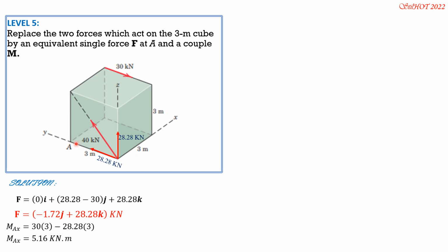MAY, because this is the AY axis and this force acts on the Y axis, so zero moment. This one is parallel to the Y axis, so zero moment. Therefore, there's no moment about Y. MAY is zero.